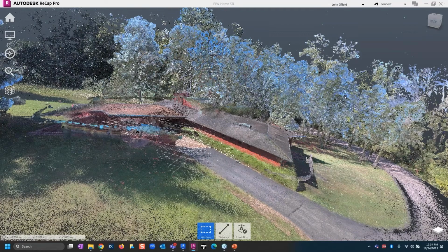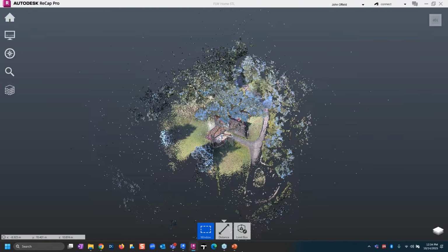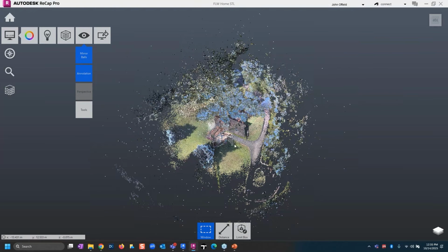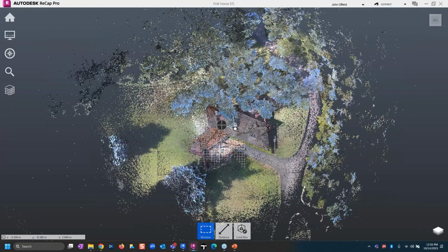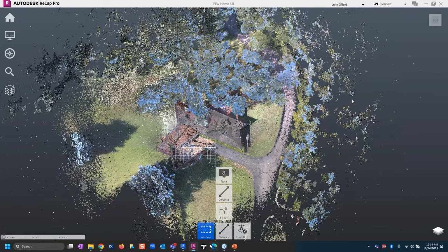Well, if you go into the top portion of your view, you're looking down on this thing. You can zoom in still just like normal, but a little tip and trick that was handed off to me just recently is, hey, what if we just turn this into an ortho type view? Well, that can work. I've always done this from perspective. So you're just going to come into your tools and left click on that perspective. It changes to that ortho type view. Makes everything a lot straighter and less of a fisheye type view here.